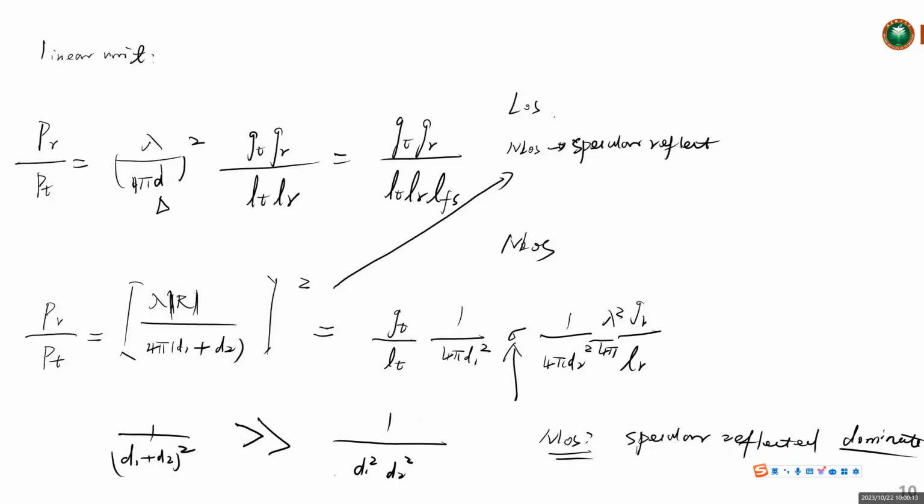So far, we have discussed the static link power budgets. In fact, the received signals are time varying, right? The received signal is always time varying. So to account for such variations, when we want to compute the system outage probability by setting up fade margins, the distribution of the variability, such as the fast and slow variations of the received signal, should be well known.